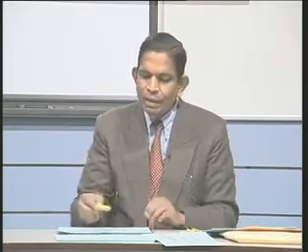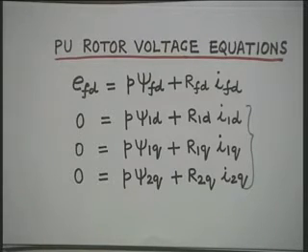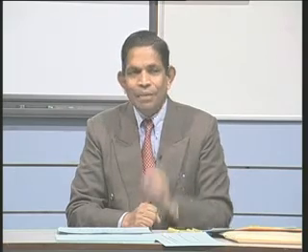The moment we neglect these 3 differential equations, we get a very important advantage, and that advantage is that the remaining equations have larger time constants, and we can use a larger time step for simulation. And once you use a larger time step, our computational efforts are reduced. Therefore, we get 2 major advantages: one in terms of reduction in the order of the system, and second, reduction in the computational time or simulation time by using a larger value of time step for integration.